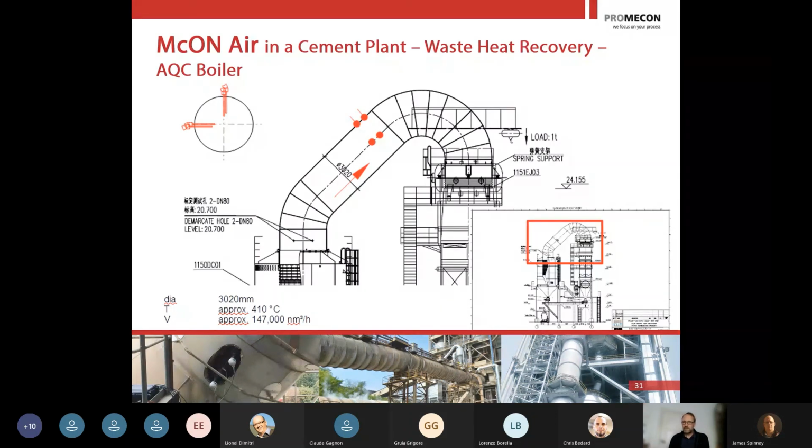The sensors have a coverage of about 40 centimeters around the sensor, detecting the electric field. But with bigger ducts, more sensors should be applied. If you have good and long inlet conditions, for example a downcomer duct with more than 10D straight section before the sensors, then you can still operate with one set of sensors.